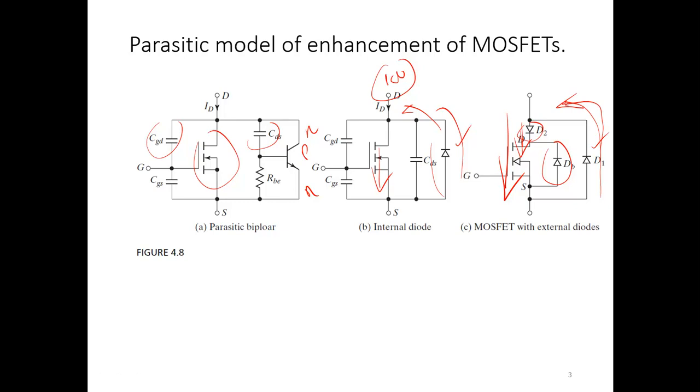That means, summarizing, a MOSFET can allow current in both directions. It's a bidirectional device unless you prevent it from being so. The warning is that the internal built-in diode will have a much lower current capacity than the MOSFET. That's why you cannot always rely on that diode to do the function you would like to have.